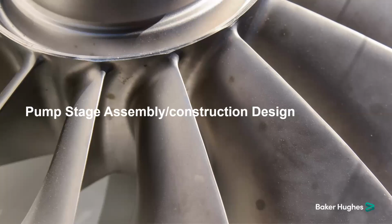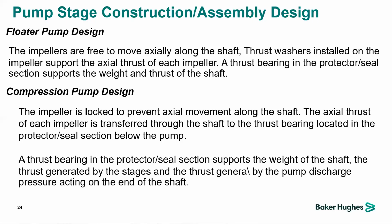The pump stage in terms of assembly or construction. Okay. When we talk about hydraulic design, that means the flow pathway inside the impeller and diffuser. But when we talk about stage construction, it is how we connect each impeller to the shaft and the diffuser, and stack all together, so the final assembly of the entire pump section, how it looks. We have two categories of pump stage assembly and construction. The first one is the floater pump design.